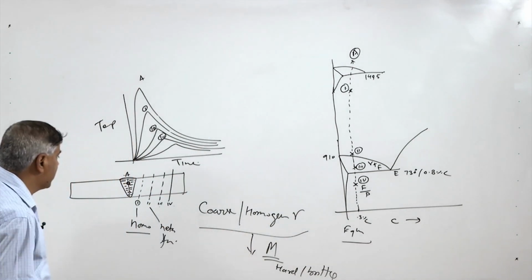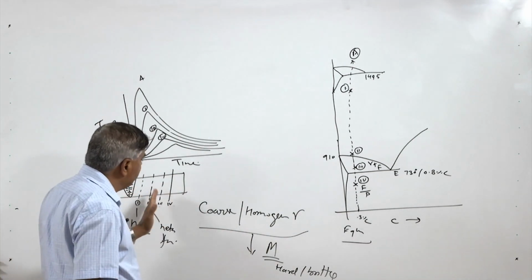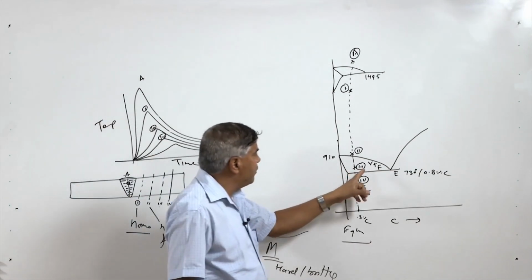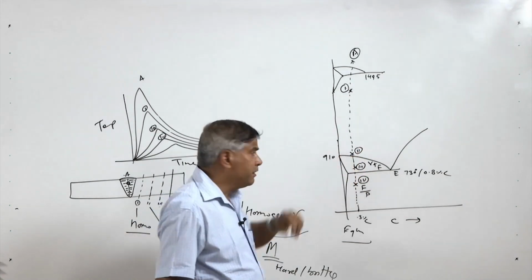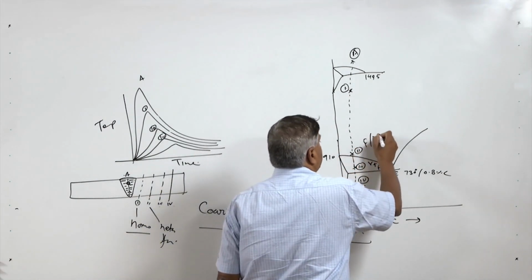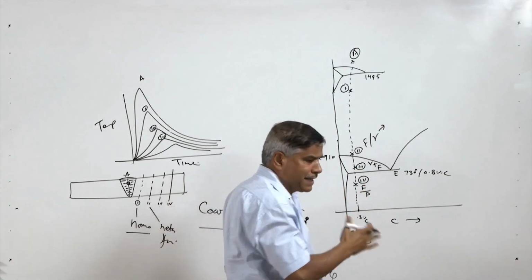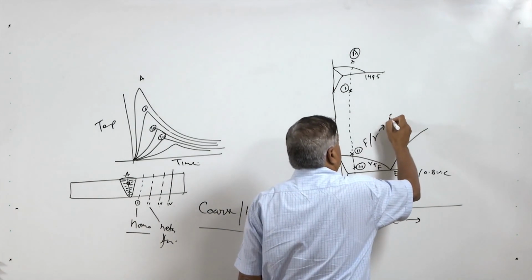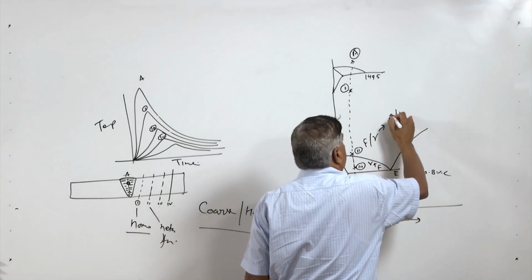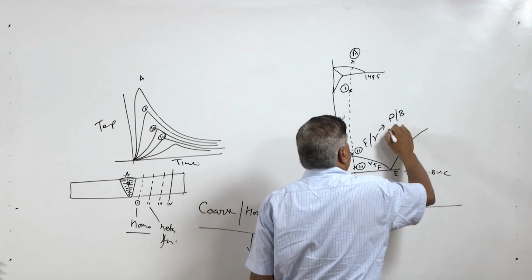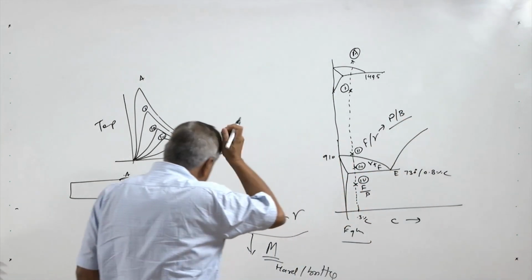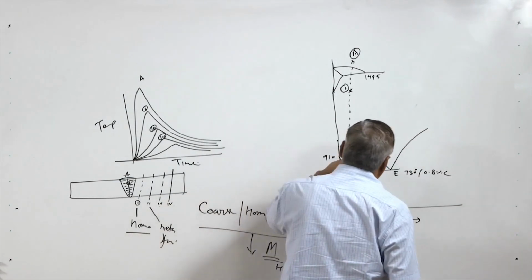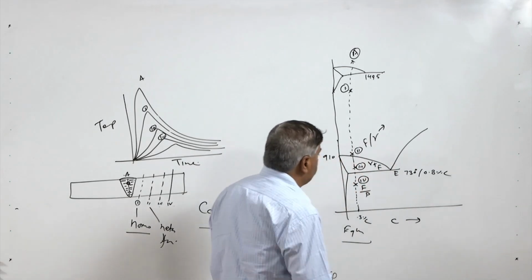So this is one typical case, while point 2, which is located further away from point 1, has fine austenite. Fine austenite discourages martensitic transformation and promotes the softer phases like fine pearlite or bainite as per the cooling conditions. Mostly it is the fine pearlite which will be produced.